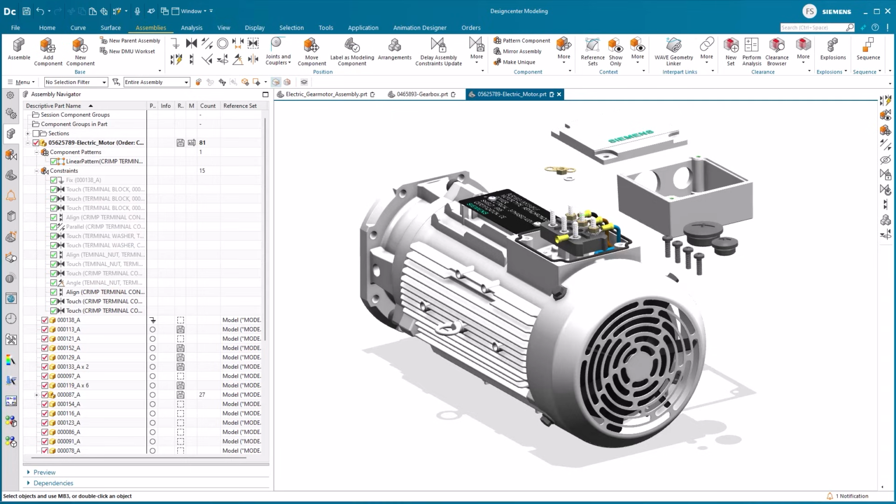Copying and pasting subassemblies or components now ends up in its original position, helping to quickly relocate the pasted version to the appropriate position in relation to the original. The drag and drop of components and subassemblies while using the Auto Align Assembly constraint is a new, intuitive way of quickly positioning your components.